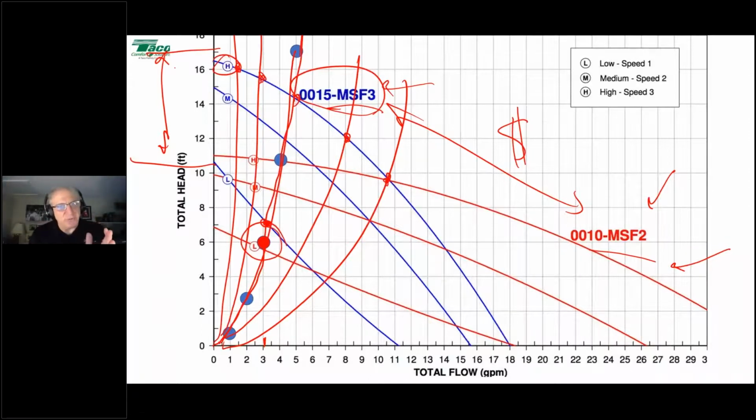But what happens is when I get up into this range, when zone valves close, they can bang, all right? When they're closing against that kind of a pressure differential, you'll get what sounds like a water hammer noise. It's not a problem with the zone valve. It's not a problem with the circulator. It's a problem with the combination of zone valve and circulator.